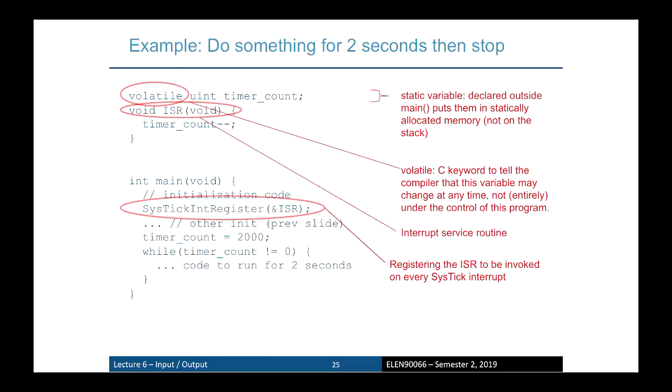Now, how you do this is you define that variable as a volatile variable defined outside of the function, so it's viewable by all the functions, but you declare it as volatile. Now, if you haven't seen volatile before, it tells the compiler that the variable may change at any time. In other words, it tells the compiler, don't ever optimize this guy out.